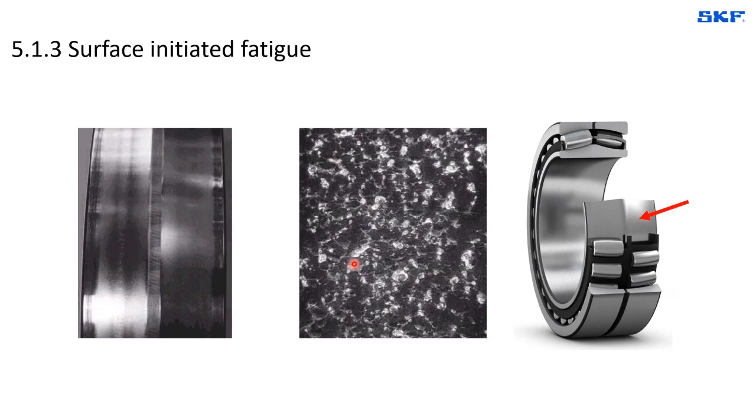We have seen also that in some cases, lubricants that have very aggressive EP additives, when they are exposed to high temperatures, they might turn acid and they attack the bearing material, leading to a weakening of the surfaces and creating this type of damage. So basically, we always recommend to use proven lubricants or lubricants that have proven EP additives.